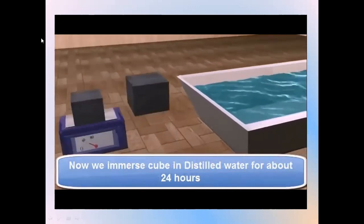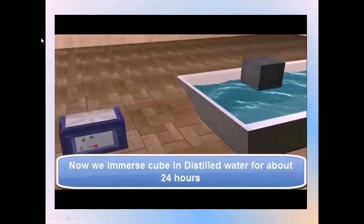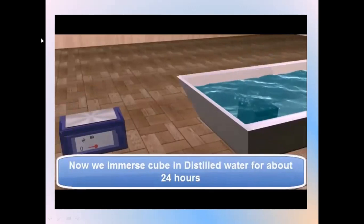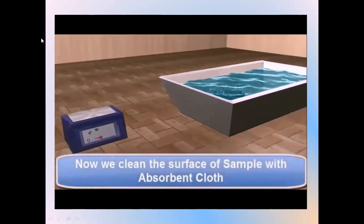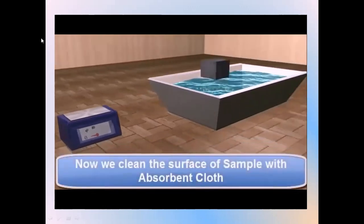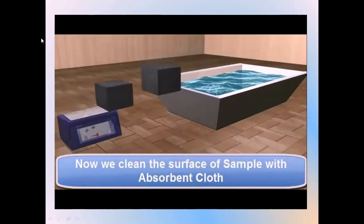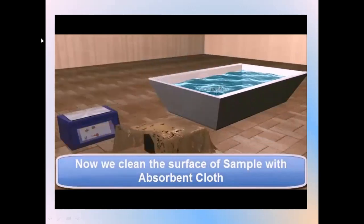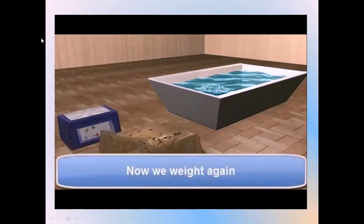Then afterwards, it is put into distilled water for 24 hours without any disturbance, so that the stone is completely immersed in water, all the pores and holes can be filled by the water, and the stone becomes 100% saturated. Then the stone sample is taken out and cleaned with a cloth so that the excess water present on the surface can be removed.